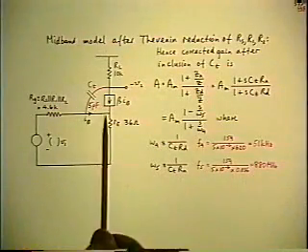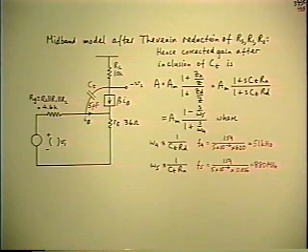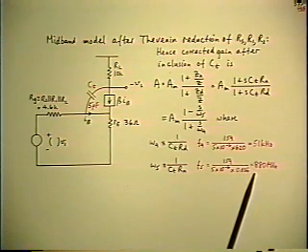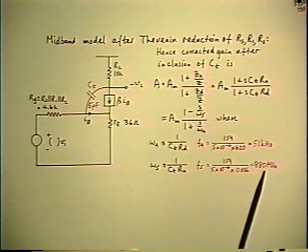Now, this is one of your basic building blocks in most of your products, I guess. So you use this all the time. Why haven't you noticed the right half plane 0? Well, this is why you haven't noticed it. It's 880 megahertz.